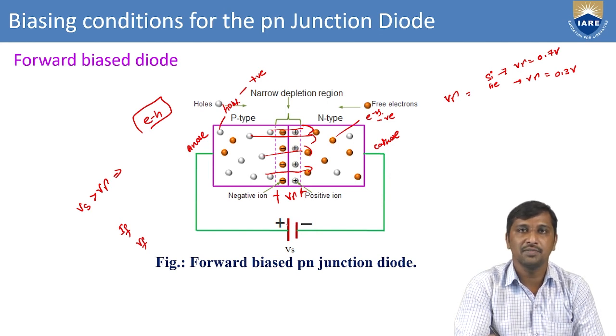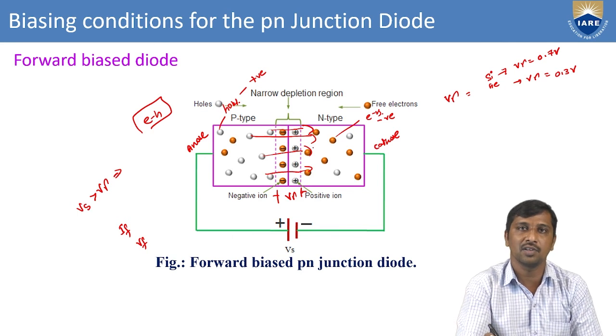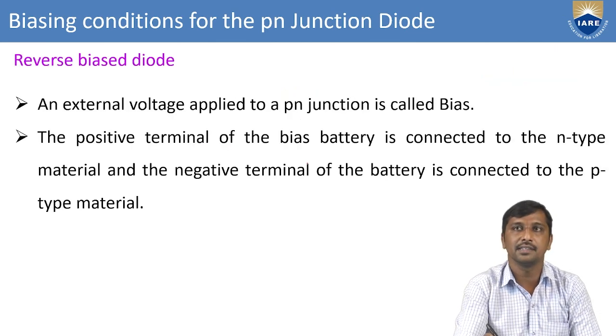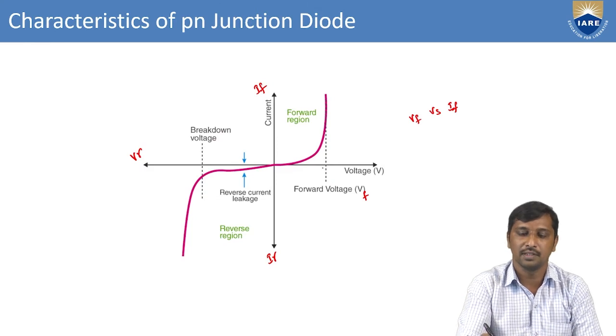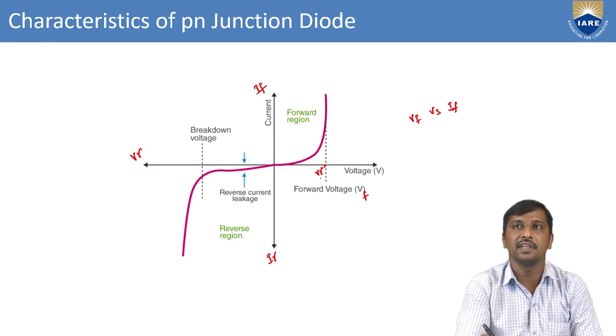Due to the forward bias operation, more majority charge carriers diffuse from the N side to the P side and from the P side to the N side, creating electron and hole pairs. Then maximum conduction takes place under this forward bias whenever the applied voltage just crosses the potential barrier voltage, which is nothing but the cut-in voltage, or V gamma.